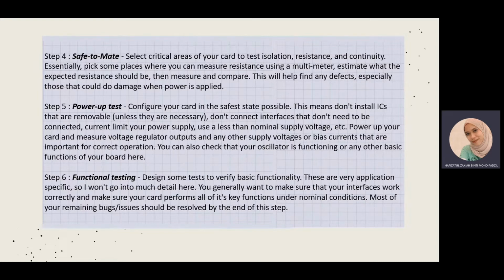Step 5. Power up test. Configure your card in the safest state possible. This means don't install ICs that are removable unless they are necessary. Don't connect interfaces that don't need to be connected. Current limit your power supply. Use a less than nominal supply voltage.